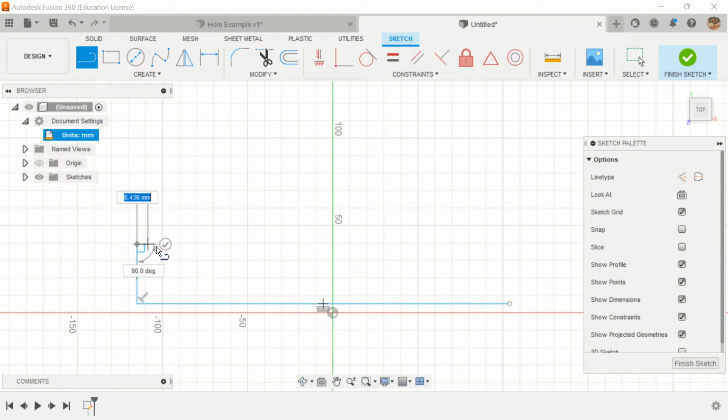Okay. Make line 3 perpendicular to line 2 and heading to the right. So notice that perpendicular constraint. You guys can't see me point at my computer screen, but you'll notice the little right angle symbol, once I clicked, turned into a little perpendicular symbol there. Okay. And heading to the right, there we go. Make line 4 diagonal and headed upward to the right. Okay. And so we just want a diagonal headed upward to the right.